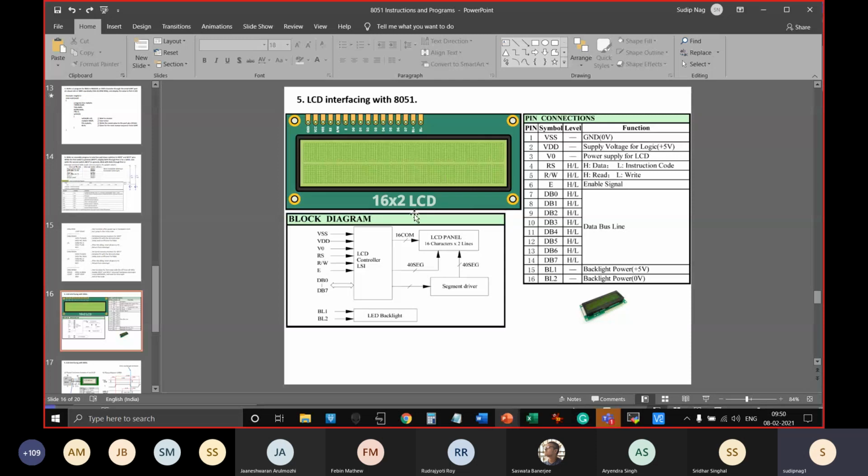It is different from an OLED display. It has different pixels where the contrast level or the reflectivity of every pixel is changed. Either it absorbs ambient light or reflects it back. That's how an LCD works. There are pixels that you can see in these dots, and those pixels are individual display elements which get lit up, become white or dark, or just vanish into the background, or show a different contrast with a different color. This is a monochrome display we are considering, very traditional and easy to understand.